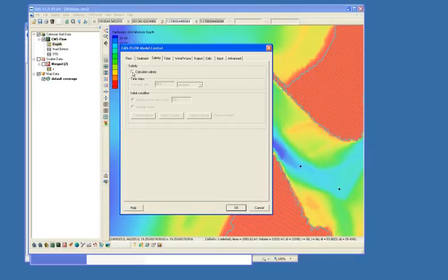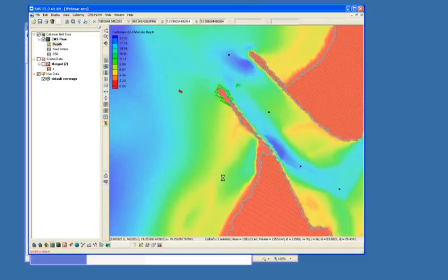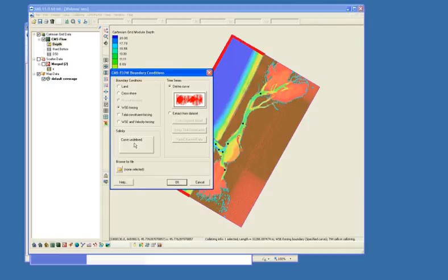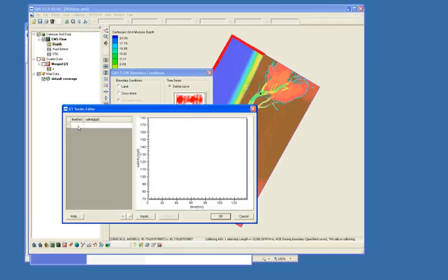That's hard to do. But the same way you would turn it on, you have a time step for salinity calculations, and then you can specify initial conditions for your salinity everywhere. And then there are other ways. Once that is turned on, then you have an option on all of your boundary conditions to specify an inflow of salinity concentration at that point.